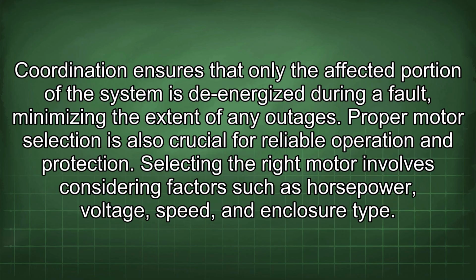Coordination ensures that only the affected portion of the system is de-energized during a fault, minimizing the extent of any outages. Proper motor selection is also crucial for reliable operation and protection. Selecting the right motor involves considering factors such as horsepower, voltage, speed, and enclosure type.